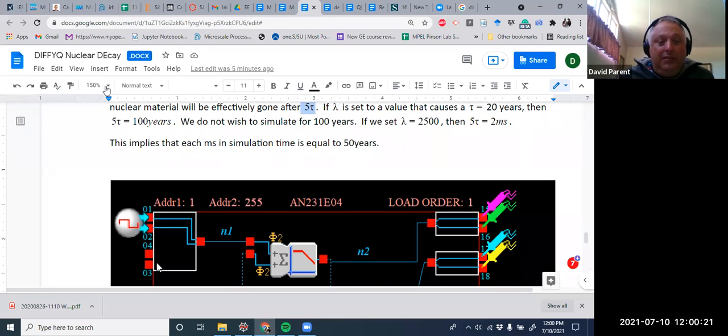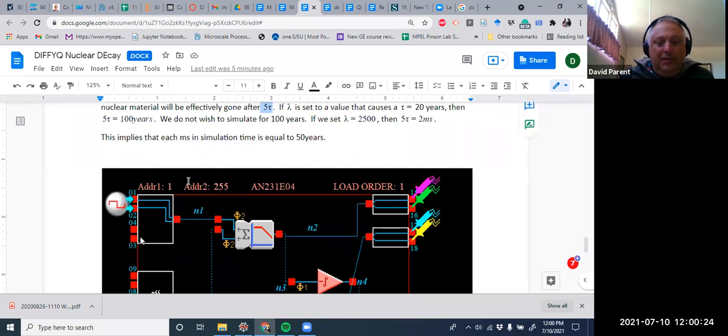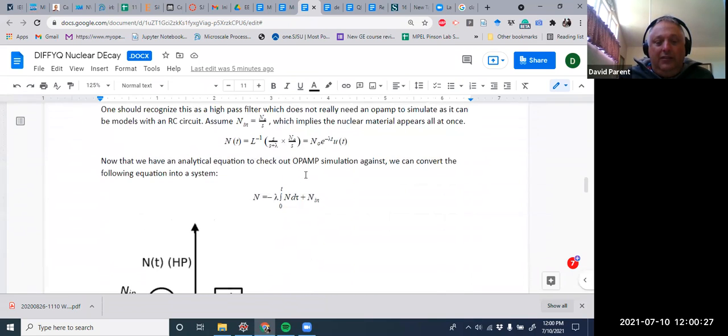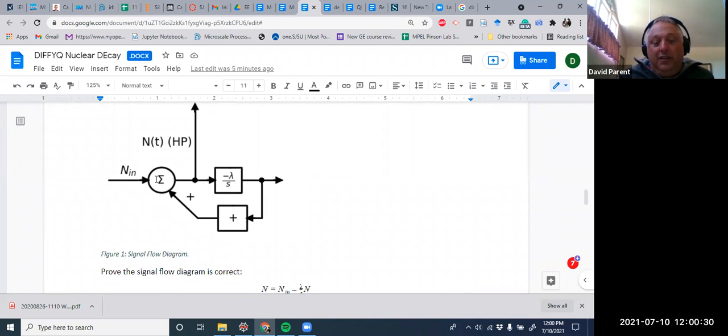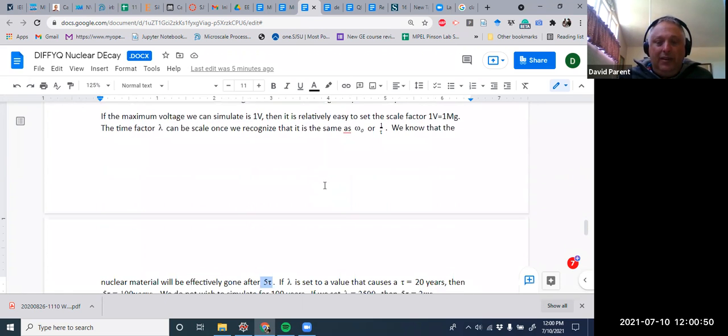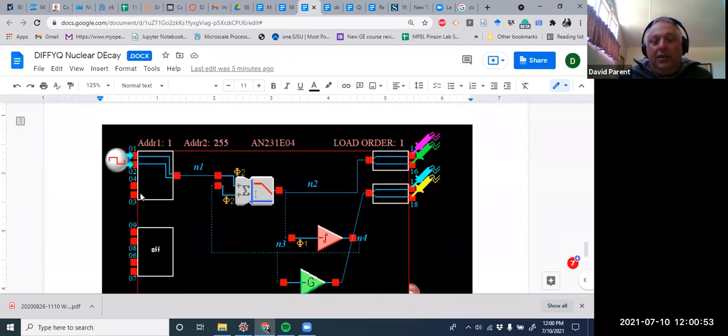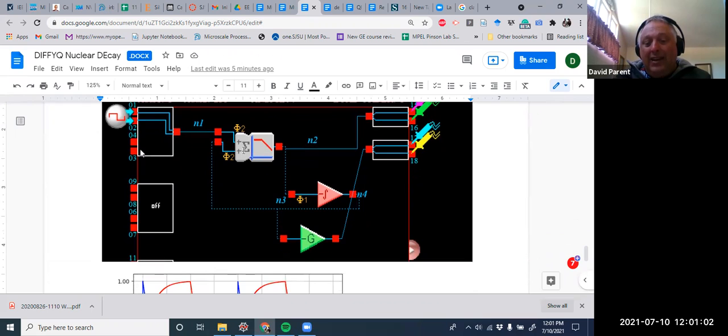Now this is a cool bit. You've done this in 110, that's a summer op amp. This is just a scale factor, it's just plus, so I can take care of all of that in the summer. And then this is our inverting integrator. So it takes 2 op amps and everything would be controlled by resistors and capacitors. But here, this is a summer and it comes with a low pass filter built in. The important part is that's where I'm adding something.